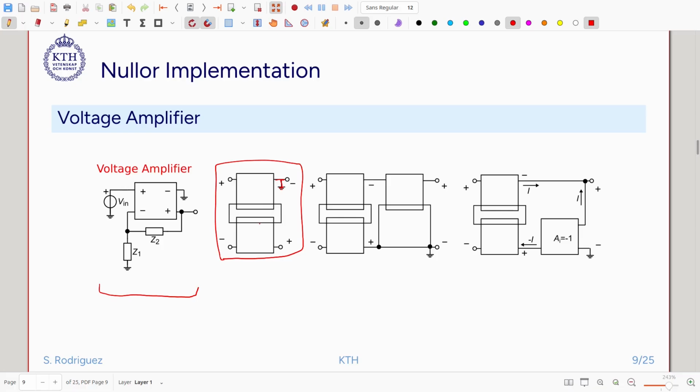It doesn't have a very large loop gain. It's a single stage, so we might want to put another stage to improve the loop gain pole product, and we can add, for instance, a common source stage. So if we add one transistor, it will look like this. So we will have the following connection, and note how I am piling up.